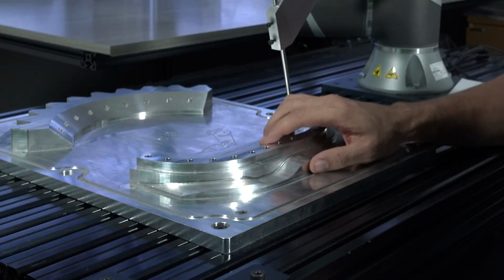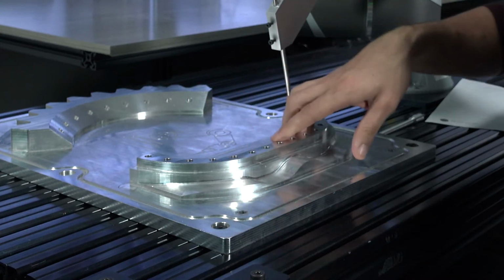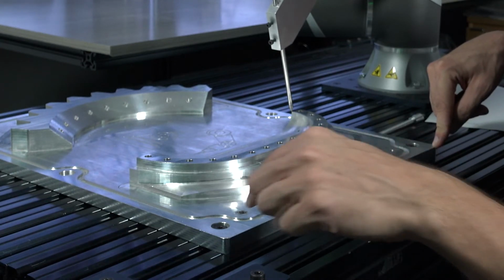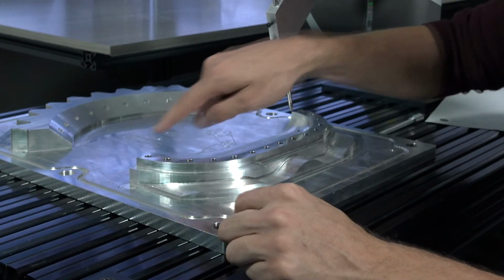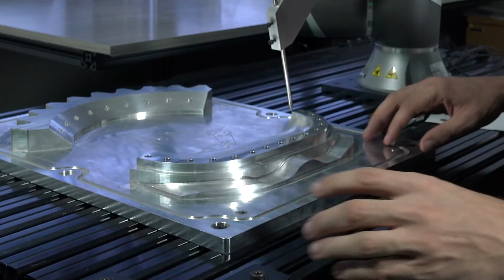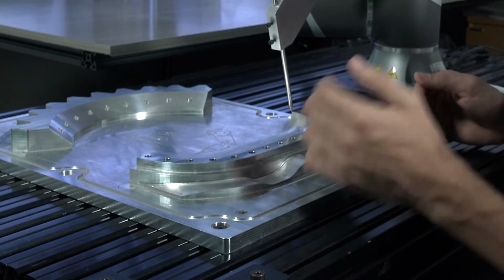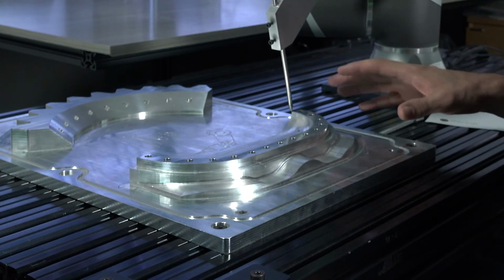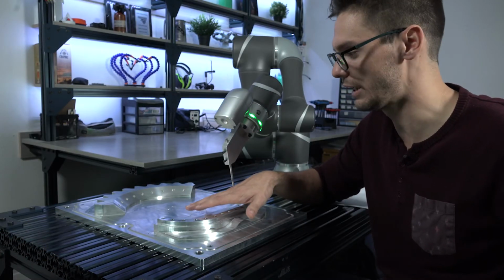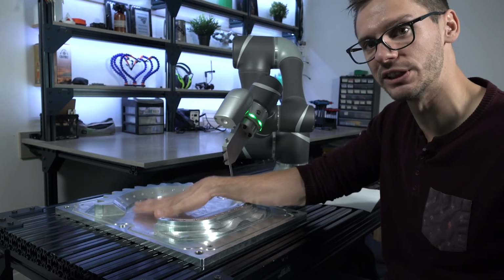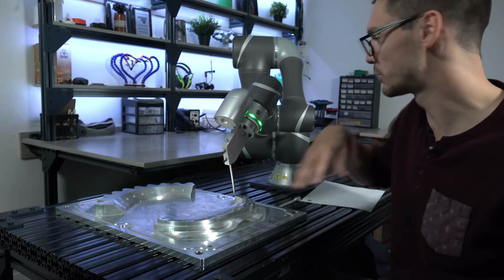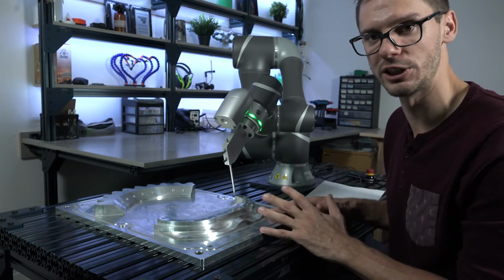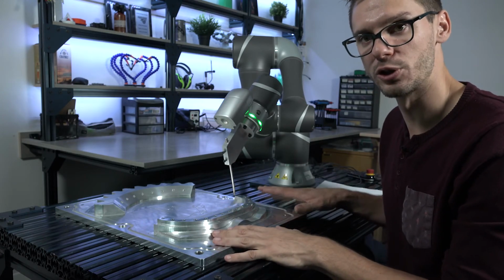So if you want to be more precise, let's say for this half of the part, one method that you could use would be to create another reference frame here or here, and create the toolpath around this section with respect to those origins. So the closer you are to the origin or the reference frame, the more precise you'll actually be. That was how you can calibrate or define the position of a part with respect to the robot base within RoboDK, so that the virtual station does match with your real station.